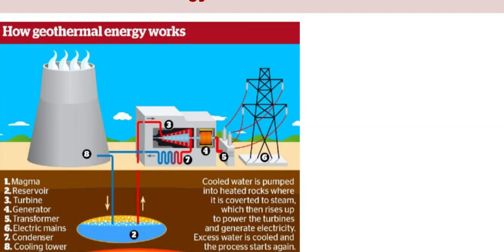Well, basically the idea is very similar up until about this point. It's different, and then the rest you'll see this whole part of generating electricity very similar. So what you do in geothermal is you're going to pump cold or cooled water down to the area where you might have magma or hot spring or whatever it is, where you have a hot location underground. That water heats up, it turns into steam, right? Okay, now we got steam. Perfect. We can send that steam through a turbine that turns the generator.